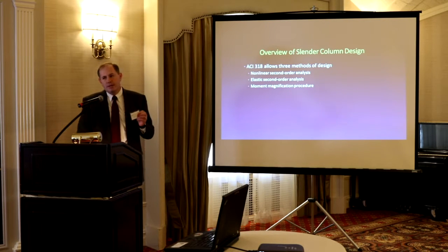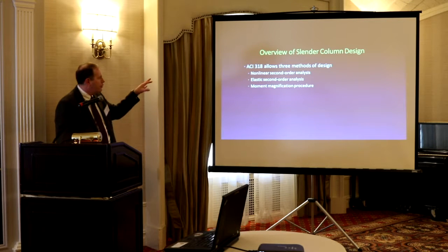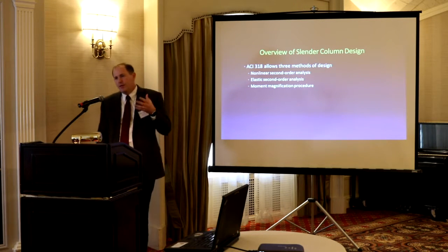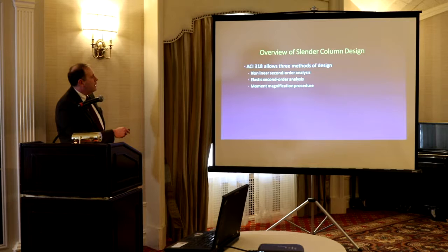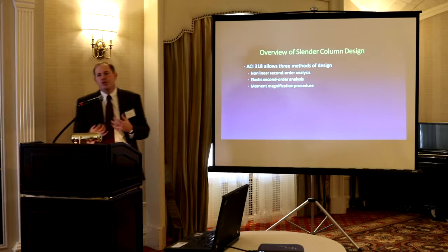Let me talk a little bit about design in ACI 318. It allows 3 different methods of design for these slender columns. There's nonlinear second order analysis. This is the most complex.